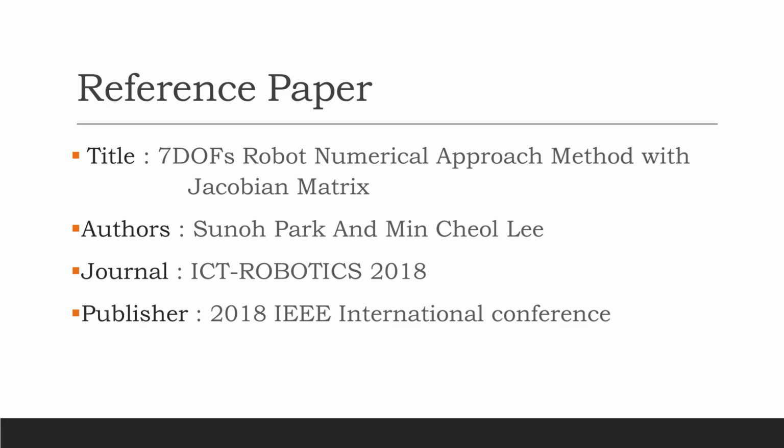As we know, inverse kinematics can be solved by the analytical method and the other is the numerical method. But it is difficult to solve by the analytical method as the degree of freedom increases. So, by using the Jacobian based numerical method, we can solve any degree of freedom easily. The research paper that we are going to study is "7 Degrees of Freedom Robot Numerical Approach Method with Jacobian". The author of the paper is